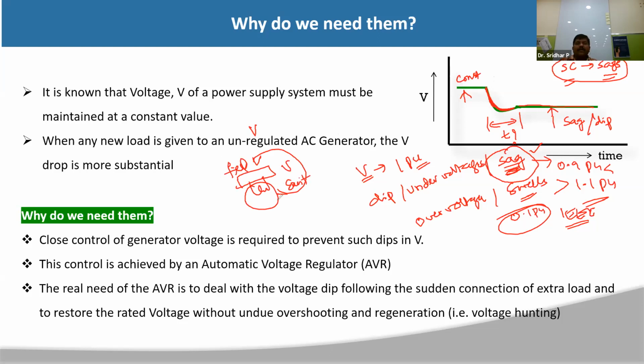In that case, if you are pulling some load onto it, what happens? The terminal voltage is already very poor because it was not properly adjusted, as there is no effective excitation loop on the system. Again, if you pull some load onto it, the terminal voltage decreases further. So that is the reason this waveform has been presented to you for better understanding.